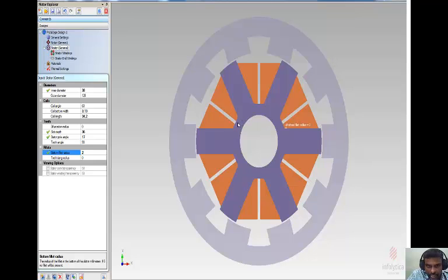So I maintained the coil bottom width as 3.13 mm, excluding the insulation. The bottom fillet radius is this one, and it is going to be 2 mm. The gap between these two is going to be 2 mm. If you want to make this 0, you can make it 0. But this is according to my design, where I make the bottom fillet radius equal to 2 mm.